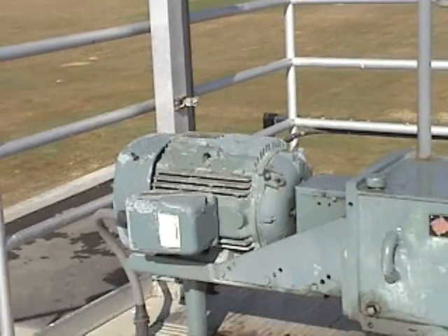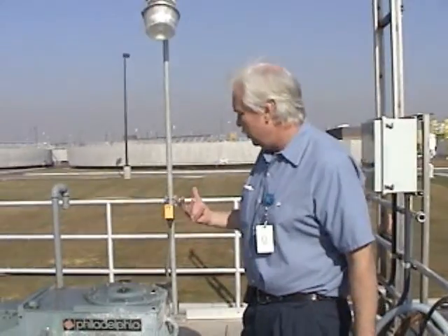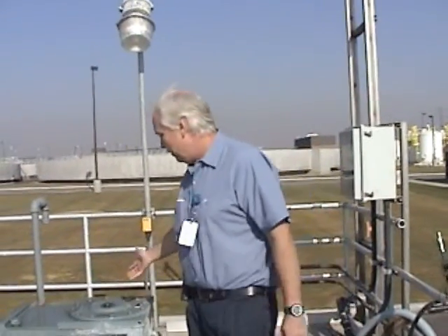If you lose this mixer, one of the signs you'll see is the influent residuals will change. When you lose mixing here at RP5, you'll have a high residual on one analyzer and a low residual on another analyzer. And that's usually the first indicator that you've got a problem with mixing. So if you come out here, you run your residuals and everything looks okay, but yet you have an imbalance. The residual over here is like 10 and the residual over on the east side is 5, I would check the mixer.